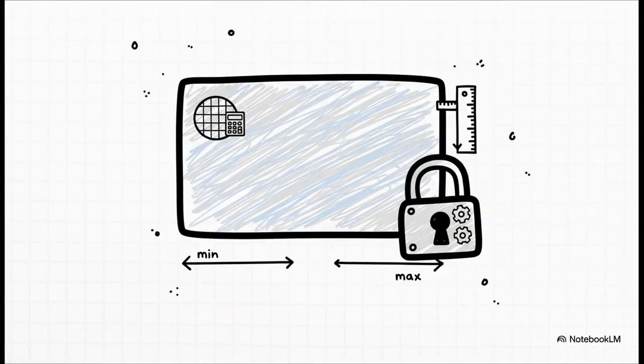So think about this for a second. For just one data field, let's say altitude, you have to define its name in plain English and its technical name. You have to define its unit of measurement. Are we talking feet or meters? You define its valid range of values, because altitude can't be a negative number. You define its required precision. How many decimal places do we need? And you define who's allowed to see it or change it. Now, imagine doing that for thousands, maybe tens of thousands of data elements. That's the level of rigor we are talking about here.